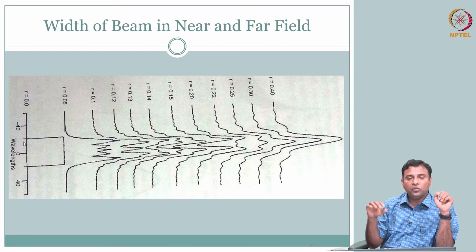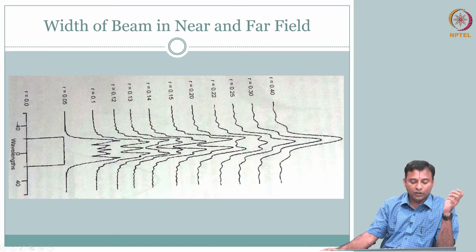So what do they do? They use some windowing, Hamming, you would have heard those terms, right. A similar thing is applicable here as well. If I have a transducer where only the crystal is here and it is cut such that there is nothing outside, so it's a hard boundary, you're going to have a lot more ripples.